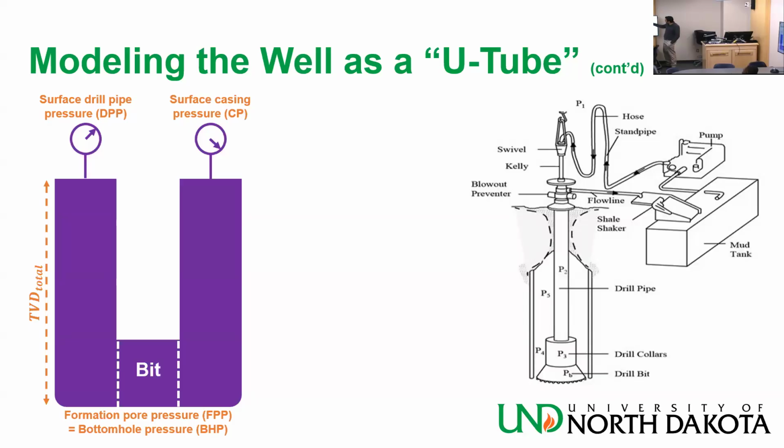And then it goes all the way into the rotary hose. It goes into the wash pipe, into the swivel, and then down the Kelly, down the drill pipe, up through the annulus, and then into the flow line, which is basically atmospheric pressure. That's why this flow line is inclined, to use gravity to help the mud go back to the mud tanks to get cleaned up. So let's just see how it works.